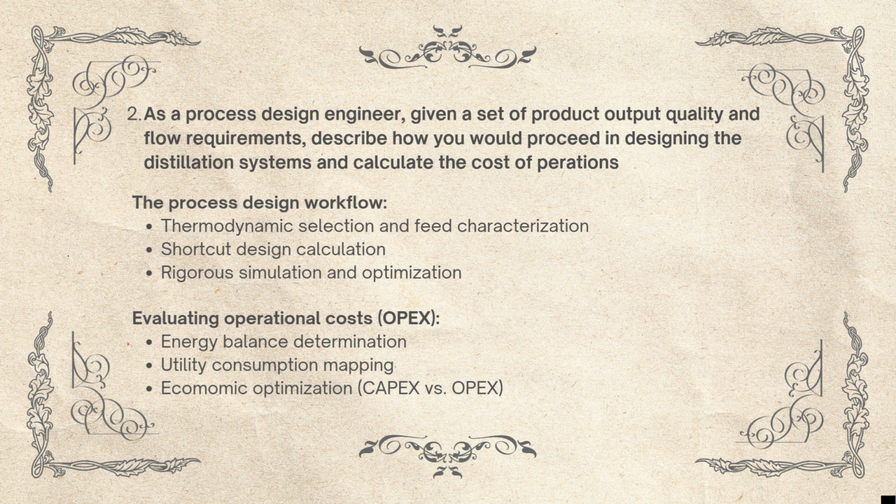The engineer performs an economic balance to find the most cost-effective operating point, usually targeting an operating reflux ratio between 1.2 and 1.5 times the minimum reflux ratio. Increasing the reflux ratio yields higher purity and a shorter, cheaper column, lower CAPEX, but drastically increased steam and cooling water consumption, higher OPEX. This requires a careful life cycle cost analysis to find the minimum total cost.